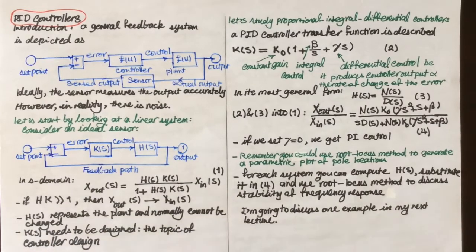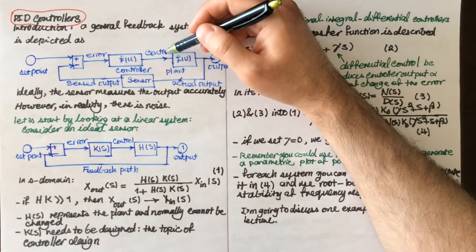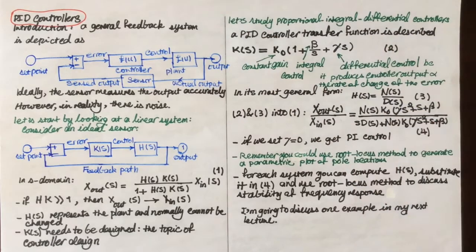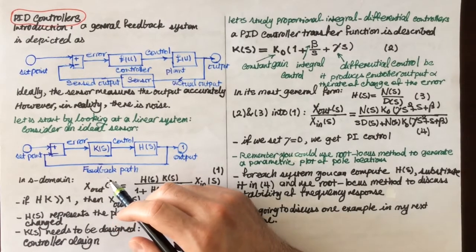So we design our feedback to bring back the disturbance, or reduce the disturbance, to zero, and based on the force that we need to use to make that disturbance go away, in the case of an accelerometer, we estimate the input force, which is related to our input acceleration. Anyway, so this is the simplest model.